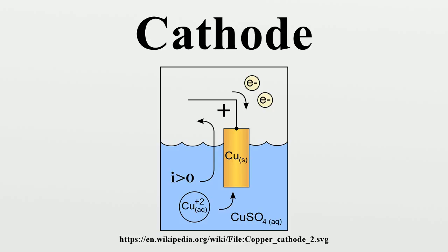It also allows the filaments in all the tubes in an electronic device to be tied together and supplied from the same current source, even though the cathodes they heat may be at different potentials. In order to improve electron emission, cathodes are treated with chemicals, usually compounds of metals with a low work function. Treated cathodes require less surface area, lower temperatures and less power to supply the same cathode current.